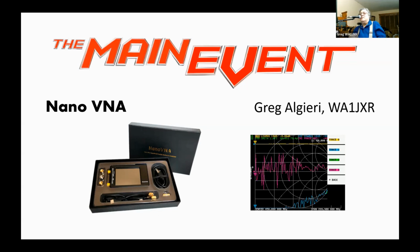But you're doing a calibration at the reference plane of the SMA connector. So as soon as you put a BNC on, I've got SMA to SO239 adapters because when I want to measure an antenna with a PL259 on it, right? And so you are introducing some error, some loss that you're not calibrating for, but because the connectors are so small, for most measurements that us hams are doing, it's not going to matter, right?